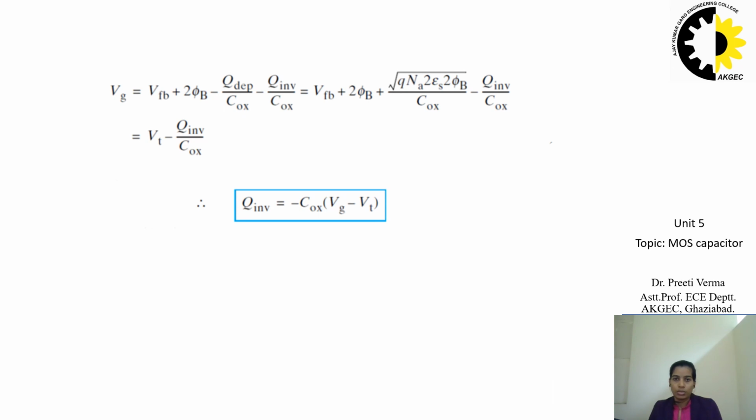So we have assumed that electrons will appear in the inversion layer whenever the closeness between EC and EF suggests their presence. However, there are few electrons in the p-type body and it can take minutes for thermal generation to generate the necessary electrons to form the inversion layer.